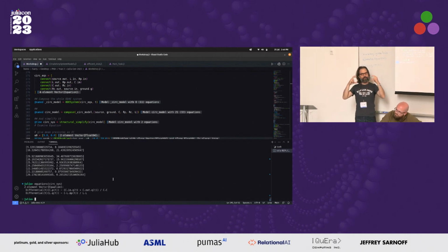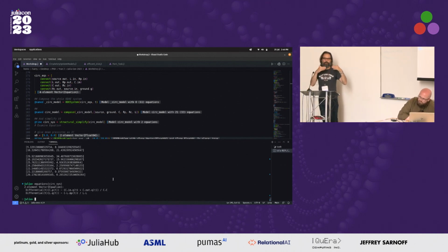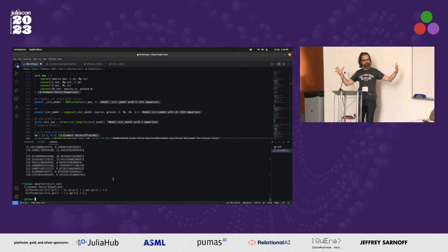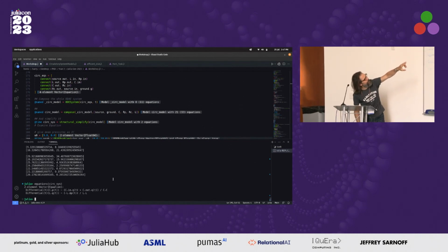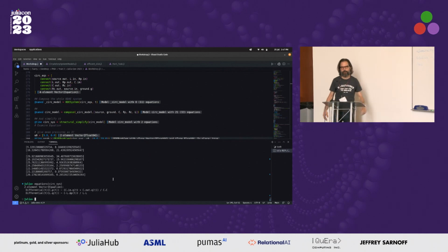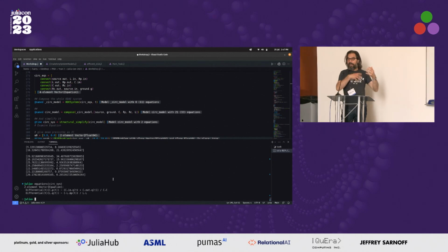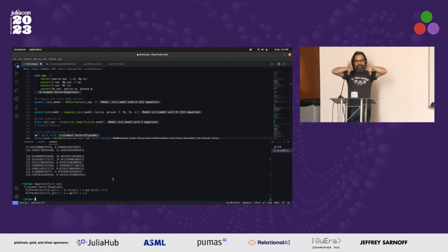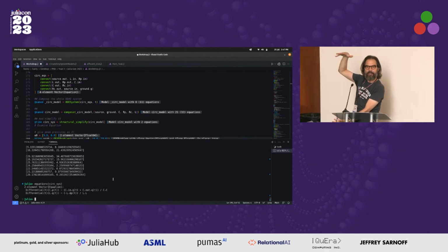Because what structural simplify does is it takes the whole system of equations apart. We look at it has 32 equations, of which 21 are ODEs. And then it takes those apart, takes the unnecessary ones out, puts them into the observed equation set, and puts the two that it wants to solve, or that you have to solve, into the equation set.